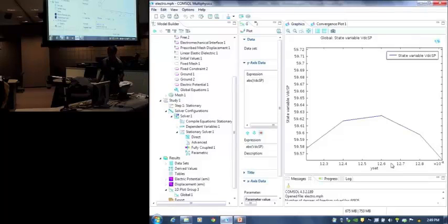For the y-coordinate. So that means if I take this particular model and in the steady state I apply a potential beyond 59.6, let's say 60 volts, this will not solve because you have reached an unstable state beyond 59.6. If you apply something below 59.6, it will solve. So that's another check that it is the pull-in voltage. I'll talk later about how you can get a transient response where you can get a full collapse of the beam.